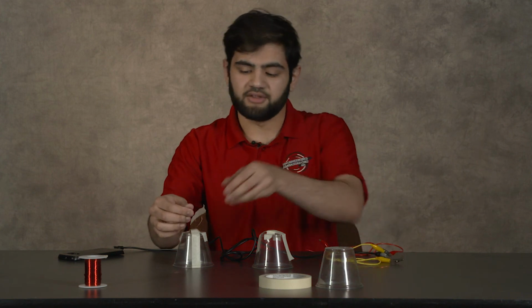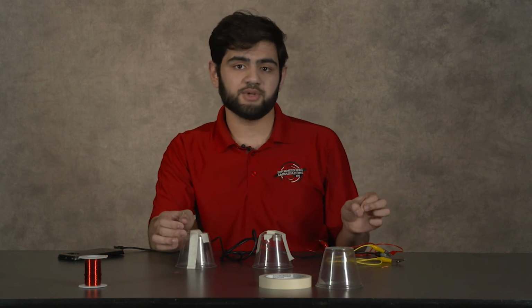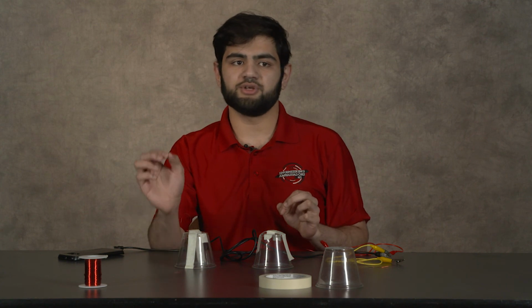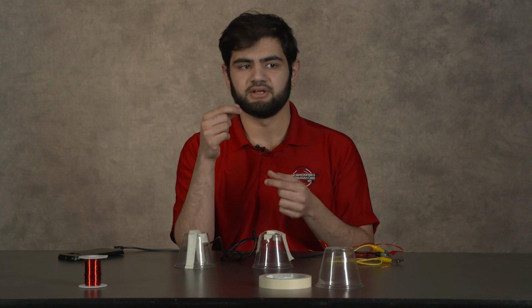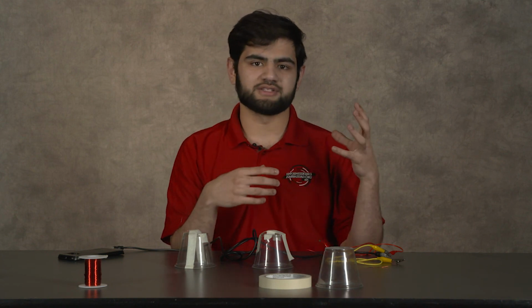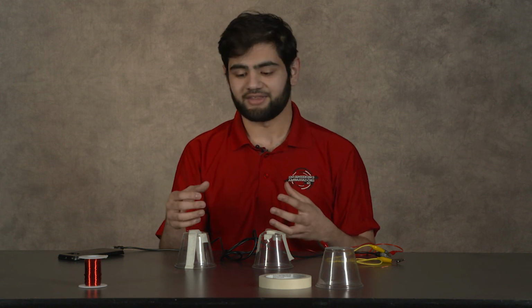So on your second speaker, have one exposed end go to the same ground as the first speaker, but make sure the other end goes to either the left and the other one goes to the right. So they should be on different signal sections, and that way one ear is listening to the left side of the music, one ear is listening to the right side, and you can get much better sound quality that way.